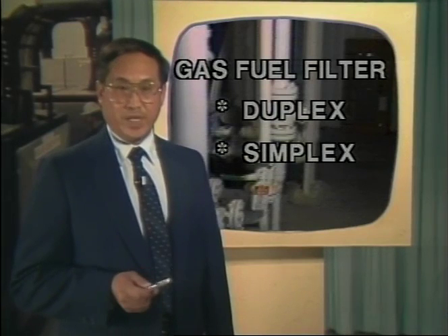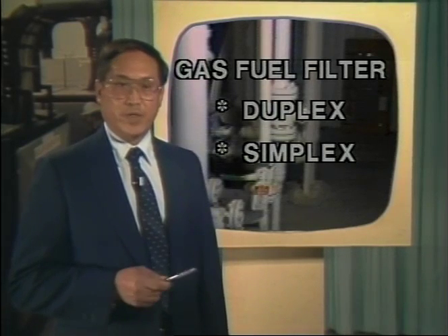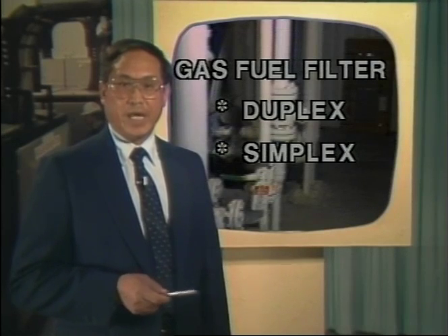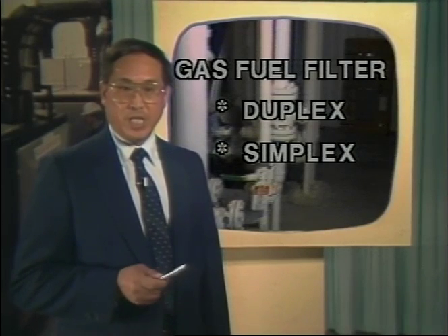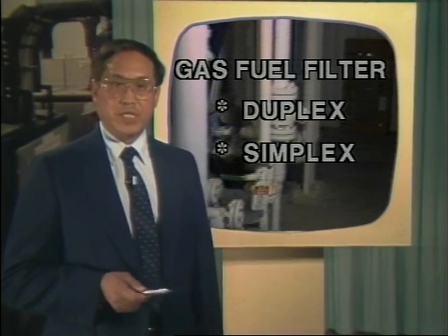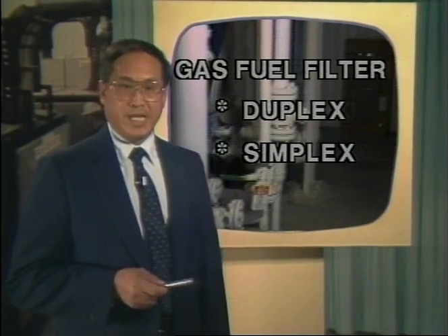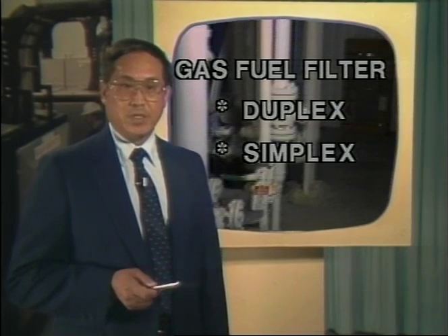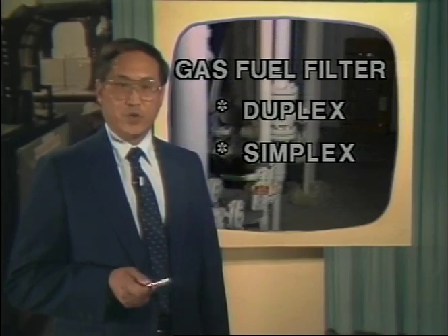If a duplex filter system is selected over a simplex system, one filter can be shut off and cleaned while the package is in operation. This is accomplished with ball valves installed in the inlet and outlet plumbing lines to each filter, providing for individual fuel shut-off.